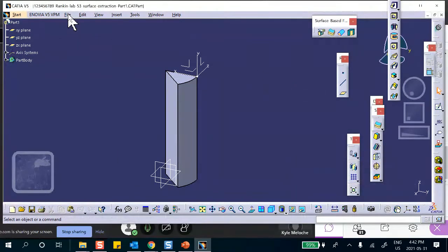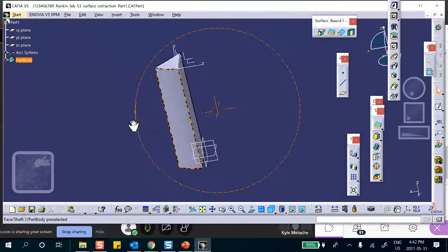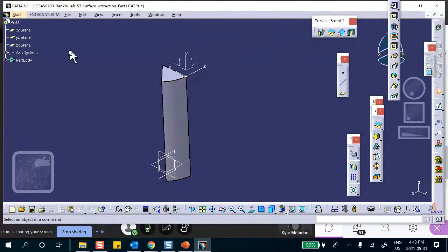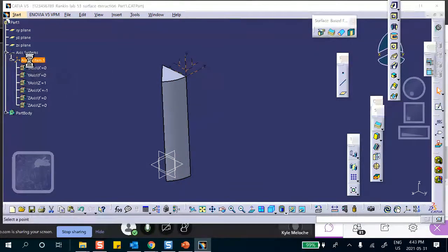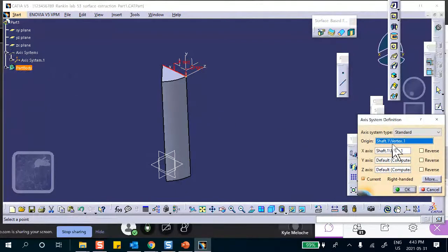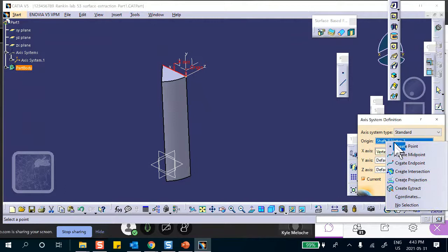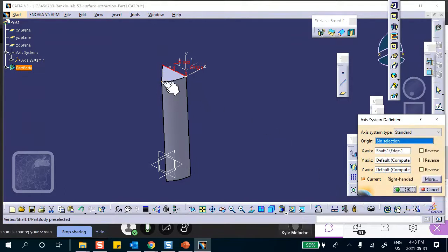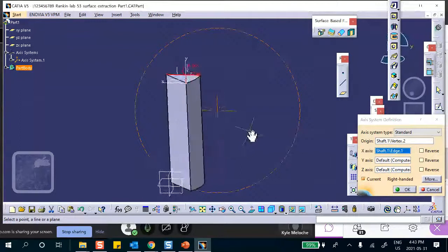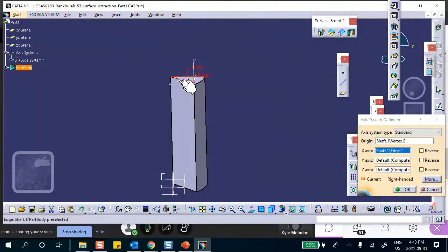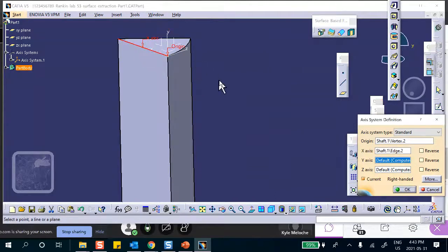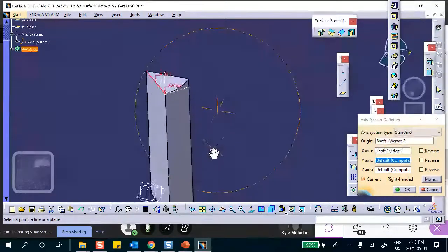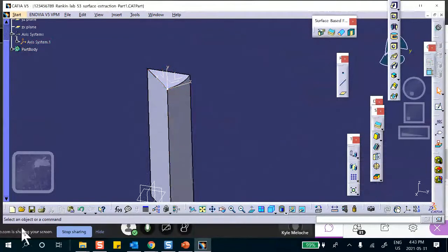Hey, Doctor. Yes. I think your axis is in the wrong plane. That's the plane that's aligned with your global. Oh my God, you're right. Thank you. Okay, let's fix it. I thought something was different. I double click on this, and let me clear that. No selection. I'm going to select this point. Okay, that's better. And now for X, I'm going to use this axis. Thank you for mentioning it, because we would have noticed it later, but anyway, that's better. Good. Okay, save everything.